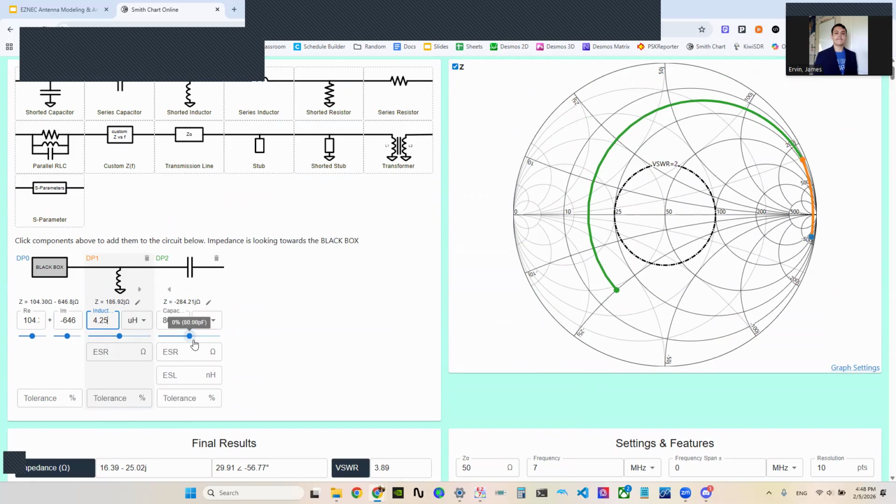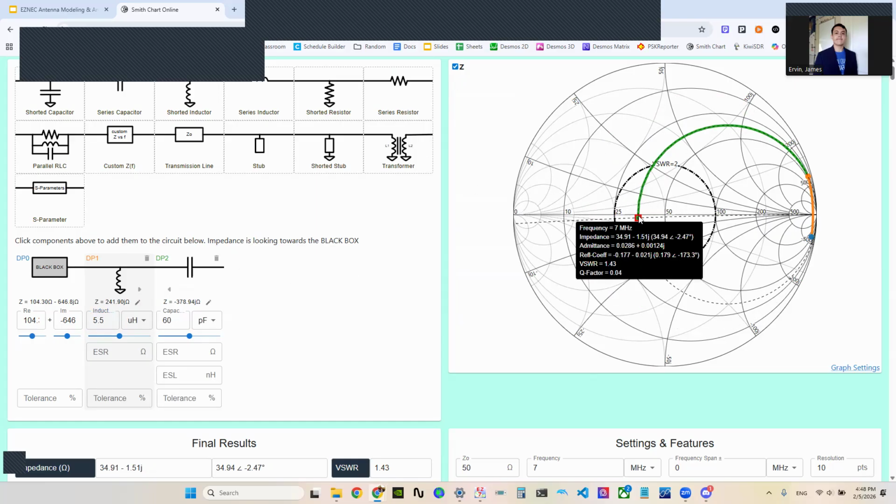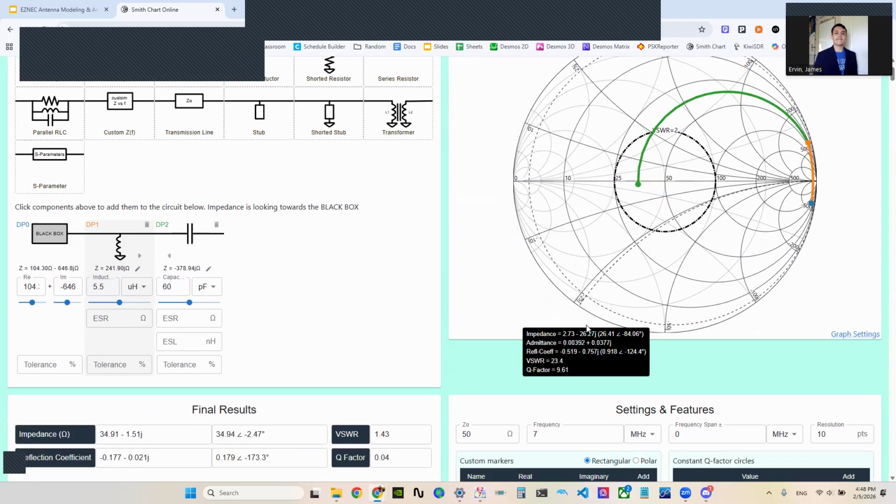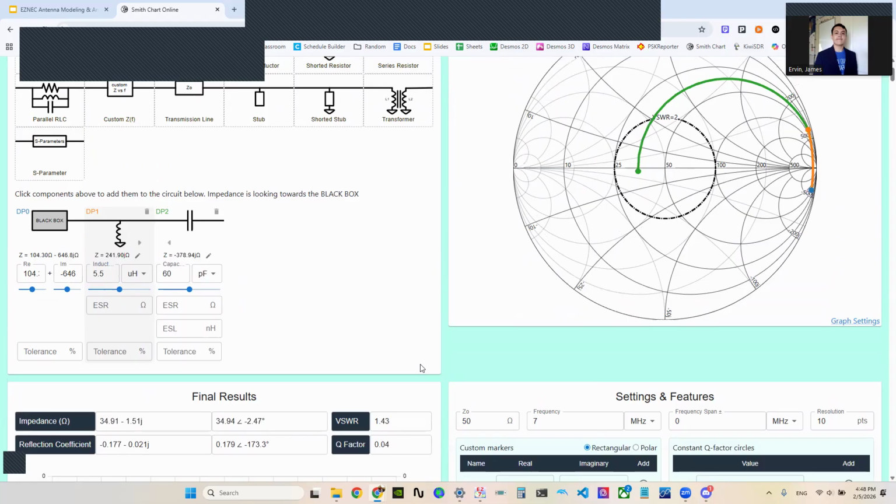It's really a little bit of an art of matching around the Smith chart. I mean, you can always calculate this stuff by hand. But I always like picking values and just kind of messing around. Because in the field, when you're deploying these antennas around your house, you're not going to have a perfect calculator always. You may only have some amount of inductance and some amount of capacitance to go ahead and match your system, right? So, okay, cool. So we have this thing resonant at our desired frequency, basically resonance here at our 2 to 1 SWR, 7.2 megahertz.